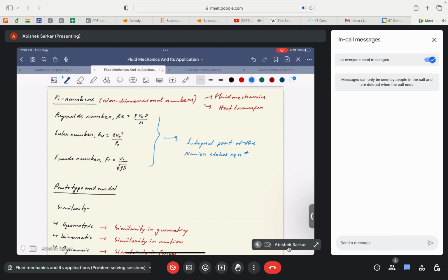See, I have written a star because right now, as undergraduate or very first year postgraduate students, this understanding is that other than the Reynolds number, say the Euler number and Froude number will eventually come into picture while non-dimensionalizing the Navier-Stokes equation, but it's actually not always the case. If you focus a bit more, it's actually not the case. Sometimes different non-dimensional numbers can also come into picture by non-dimensionalizing the Navier-Stokes equation, given that there may be different driving factors or driving forces that may drive the flow, right?